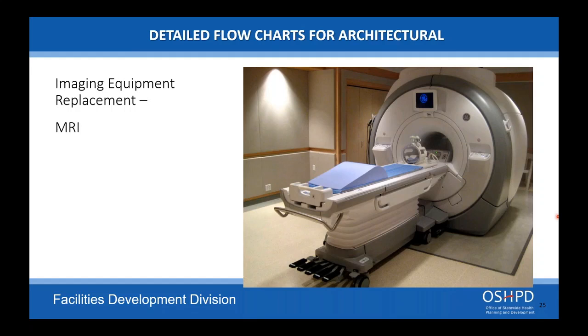Now, the room would require accessibility around the new imaging unit. You still have to have your clearance, your 3 feet around the table, and you are allowed to do any construction required to replace the new equipment. If you had to remove these doors and replace them, or a new control station, that's fine.